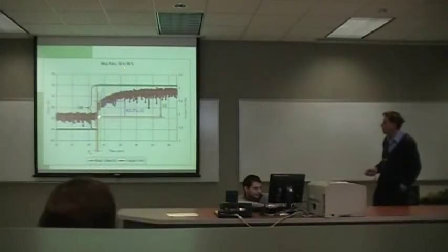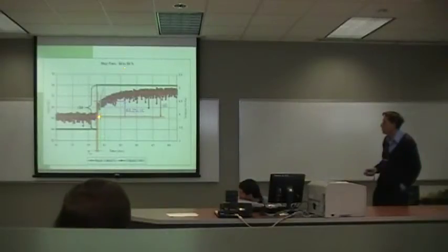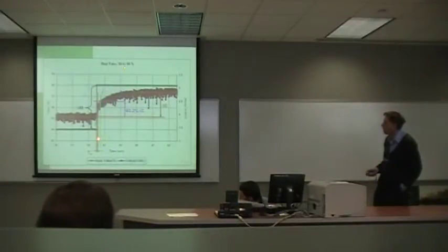And you draw a line through here, as you know, and where that line crosses this line, the distance between where you initially start the change to where that comes, that's your value for T sub O. You then take 63.2% of your change of our voltage, you draw a line on here and then come down, and that line between that and where the dead time ends, that is your time constant.